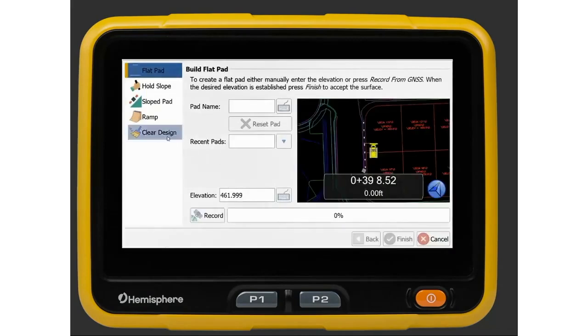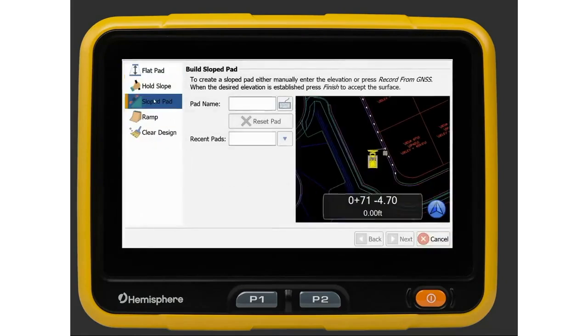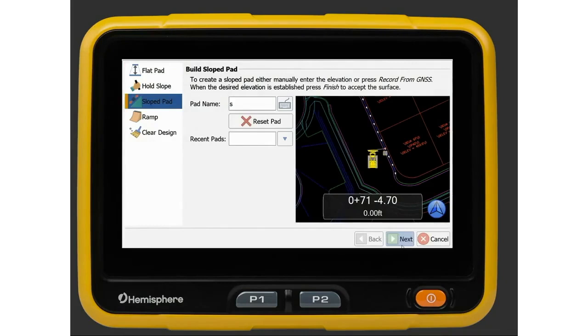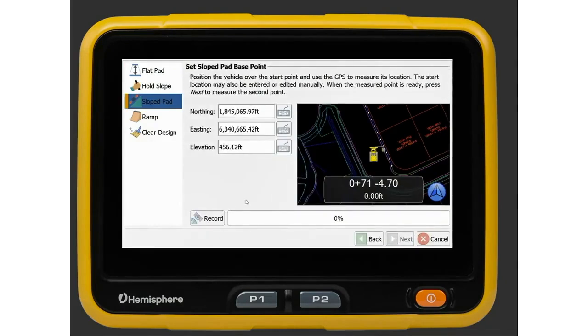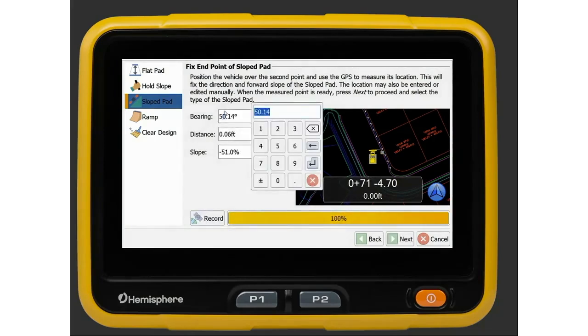This will do anything a dual plane laser can do, useful for parking lots, tie-ins, and 2 known areas. To start, position the machine on a known grade or stake and facing the direction of the proposed mainfall slope. Now press Record. And now Next. You would now drive the dozer in the direction of the mainfall heading, and you can also place the blade down to establish mainfall % between the 2 points, or you can type it in manually if needed. I cannot move the dozer in the emulator in this menu, so I will just type in the bearing, distance, and slope, and select Record.